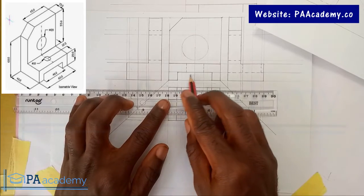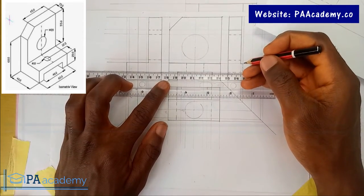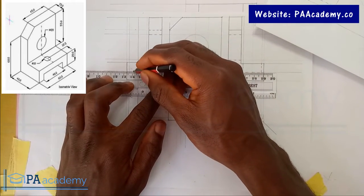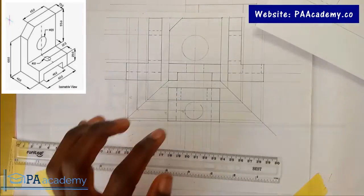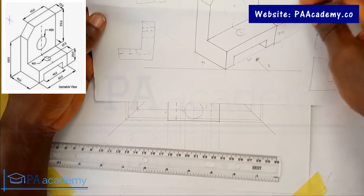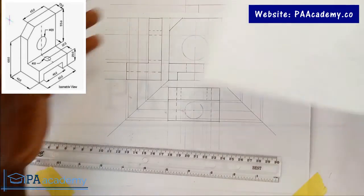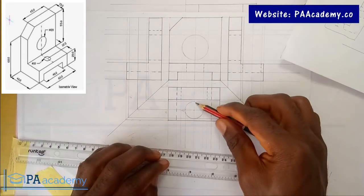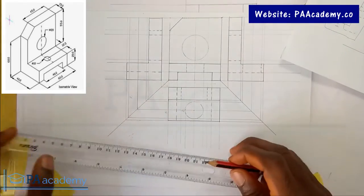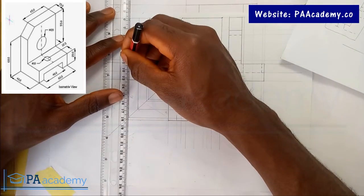So just underneath here, so you can see, we just have to show it here too. So the last thing there is this opening here. Like I said earlier, this opening, if you're looking at it from this side, you won't see it, but it's there. So indicate it with short dashes. Exactly. So now we just trace the circle. This is the circle here. So we just trace the circumference of the circle. This is one, and this is the second one. So this will be the line that will indicate that.